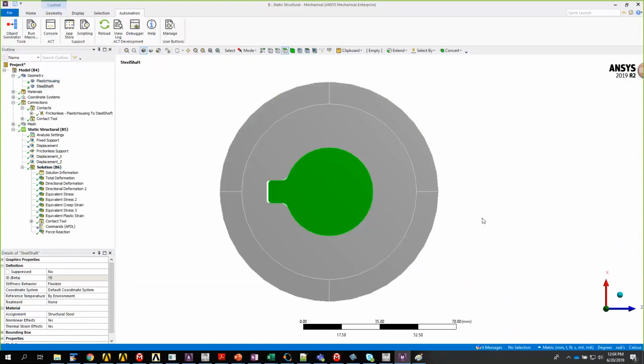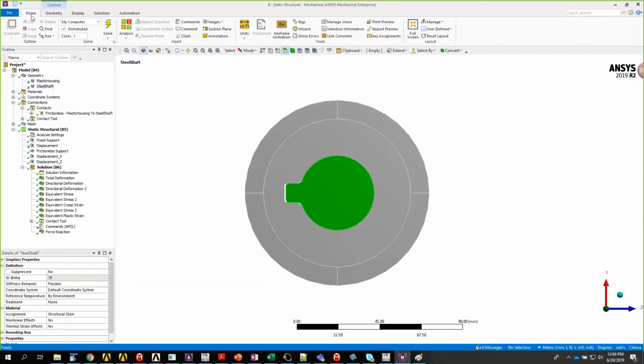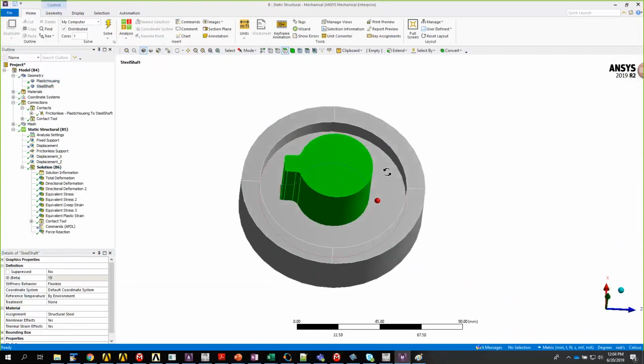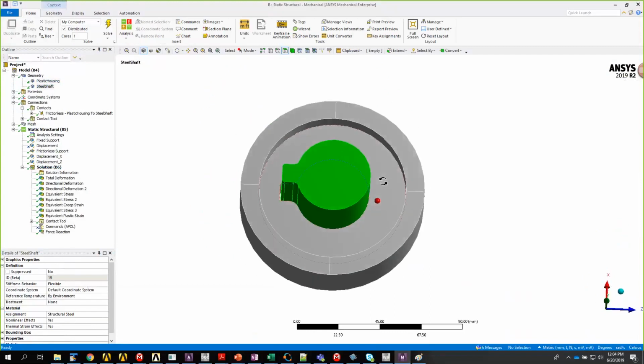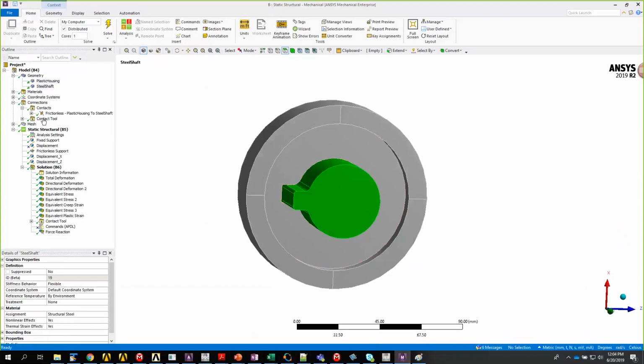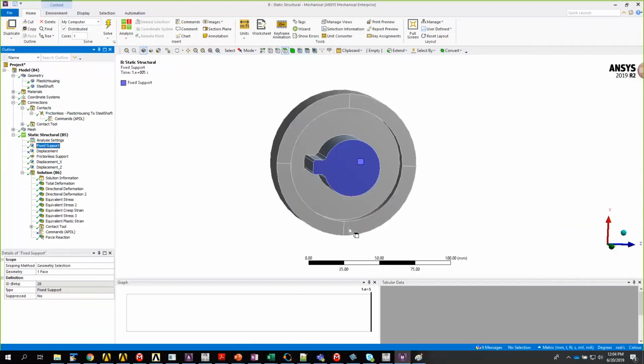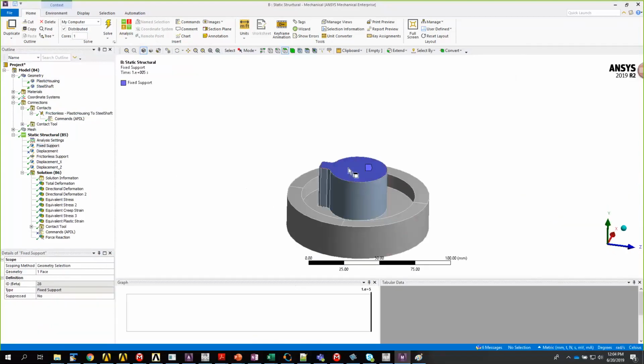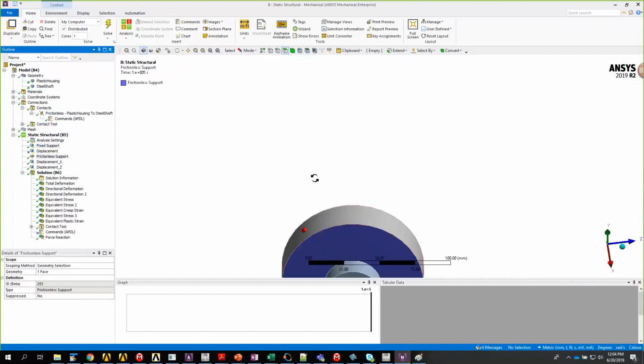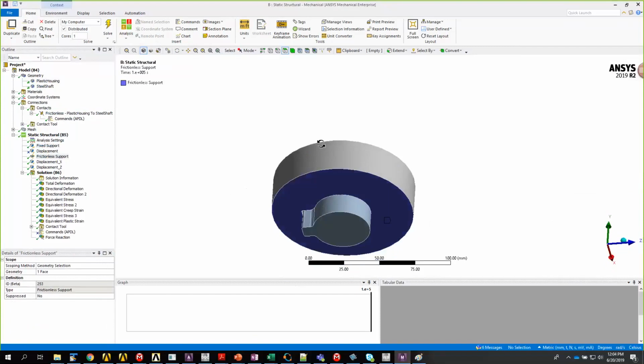And if we look at the material, I haven't really modeled any interference as such between the components, but instead the interference is given in terms of the contact offset. So initially I'm starting with 0.1 mm offset. Then what I'm doing is that this shaft is fixed. We are just resolving the interference fit, and the bottom is sitting on a kind of a table or a plane.